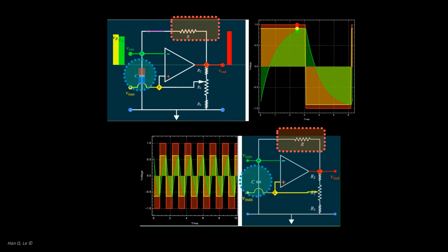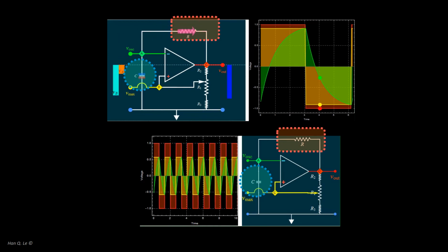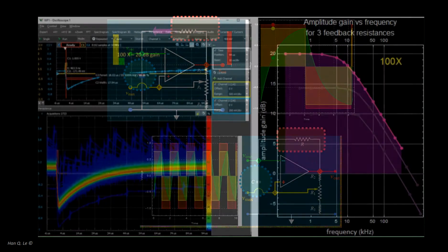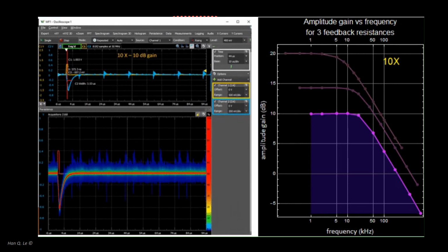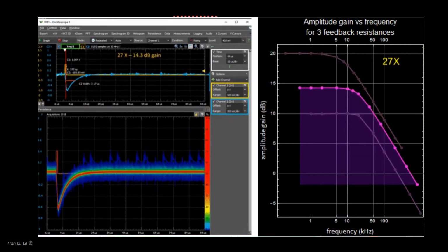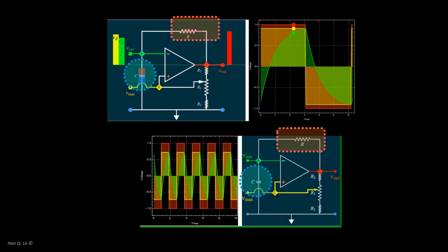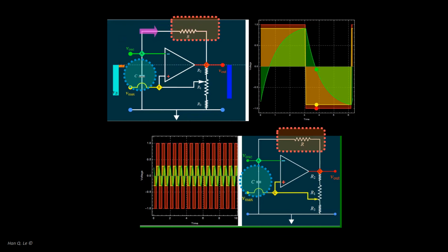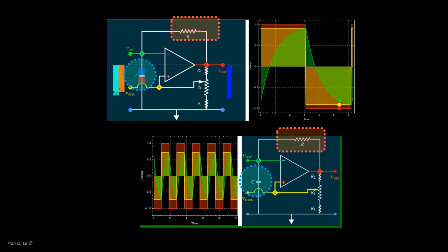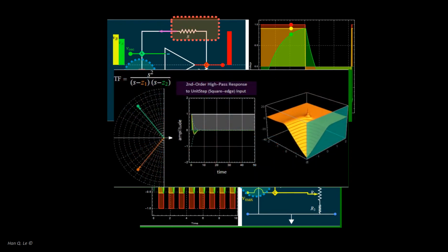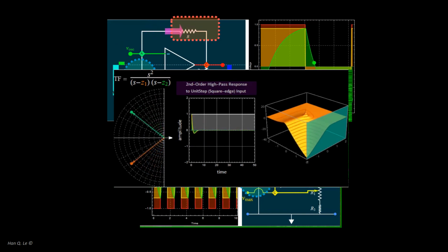Here, once again, there is a link between the characteristic response time versus the frequency, like what we learned in Lab 4 Part A. The shorter the characteristic response time, the faster the circuit oscillates, analogously to the impulse response time versus the frequency bandwidth that we learn in Lab 4. In circuit theory, you see that the RC characteristic time is a key parameter of the circuit frequency response behavior, and for the linear Laplace transformed circuit, each RC time is a root or pole in the circuit frequency response function that defines the circuit behavior.